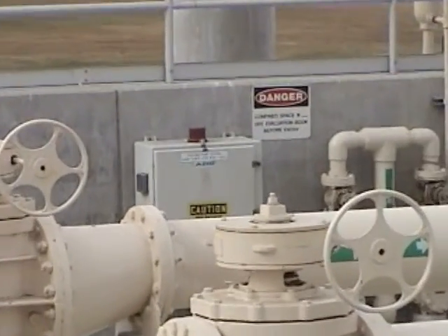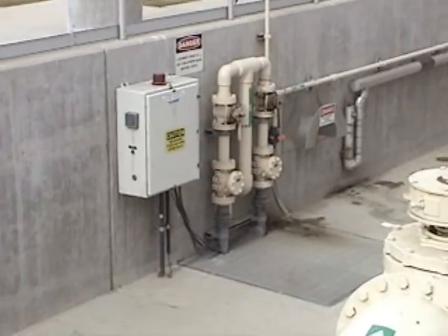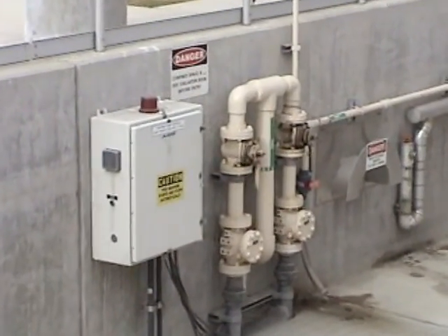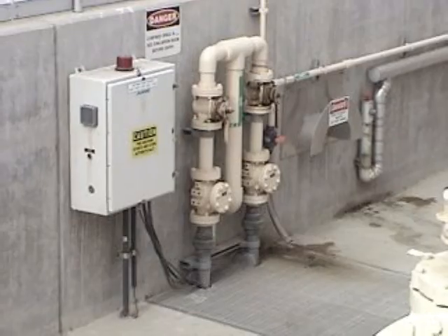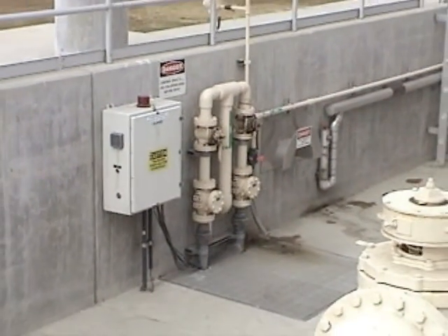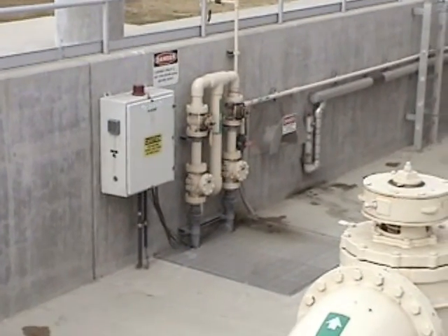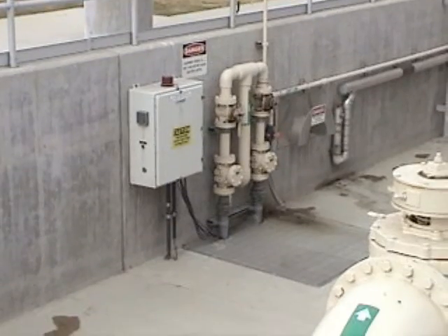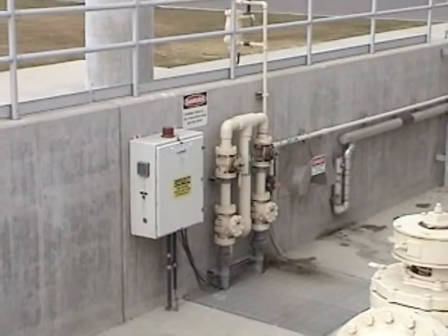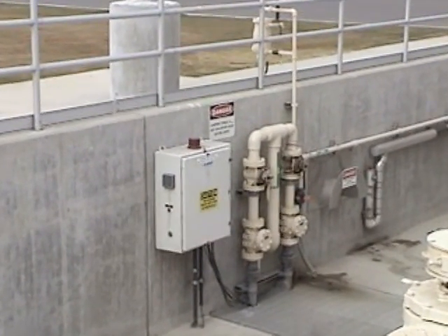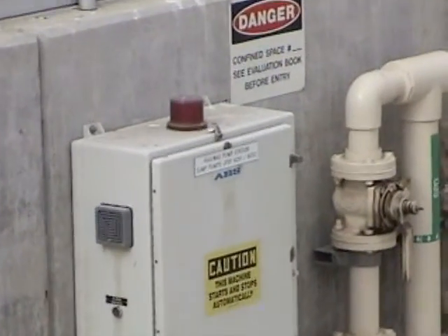That particular cabinet and sump pump configuration is used throughout the plant. There will be 2 sump pumps in the sump over there. They'll run in hand or auto, and they're controlled by float switches, and there will be an alarm for high level and high-high level. As the level in the sump increases, it'll turn on first the lead pump. Then if the level keeps increasing, it'll turn on the lag pump, and at that time it's going to sound a klaxon, set off that beacon right there, and it's also going to signal the SCADA system that you have a high level in this particular sump.